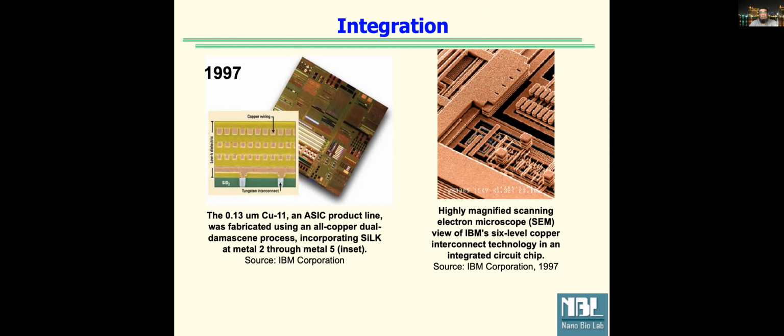This is an SEM picture, a scanning electron microscope picture, which shows you just 6-level copper interconnects, where everything has been dissolved, etched away to show the detail of the copper that remains. On the left-hand side, this picture shows that these copper wirings are made on silicon. Silicon is where you would have made devices.